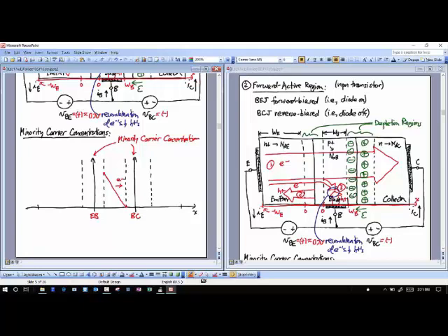And unfortunately, there is. And that's why we have to worry about things like finite input bias currents into op-amps. That is a bipolar phenomenon. And that finite input bias current is exactly this current going to the base of this transistor. The input to your 741 op-amp is two bipolar transistors, the bases of two bipolar transistors, and that current is flowing because I've got this current happening.